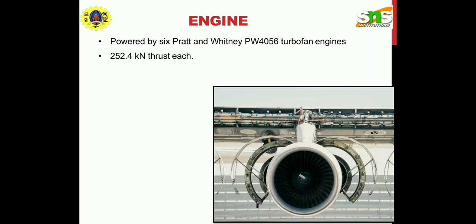Radial flow turbo machines: when the path of the flow is wholly or mainly in a plane perpendicular to the rotation axis, the device is termed a radial flow turbo machine. Therefore, the change of radius between the entry and the exit is finite. The radial turbo machine can be inward or outward flow type depending on the purpose to be served. Outward flow type increases the energy level of the fluid and vice versa. Due to the continuous changes in direction, several radial stages are generally not used. A centrifugal pump is an example of a radial flow turbo machine.